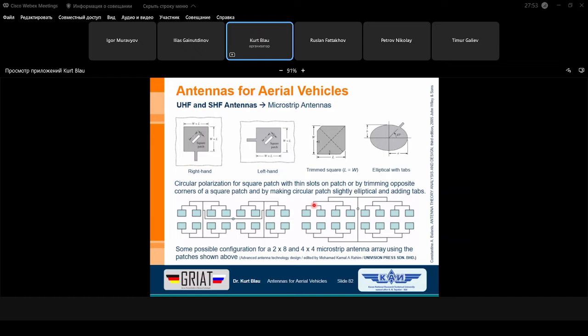And so we have to insert, for instance, transformers, to make from 50 ohm, along the transformer line, for instance, 100 ohm. And then at this feed point we have, again, because of the parallel connected elements, 50 ohm. All these things we have not discussed, but I only want to mention it so that you know it's not so easy to design such a group antenna or an antenna array.